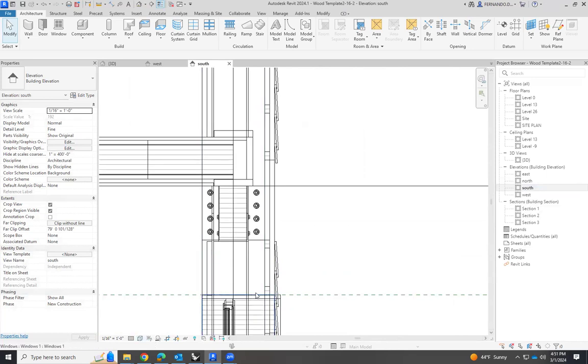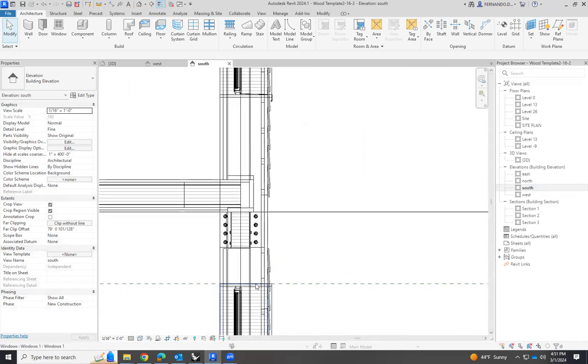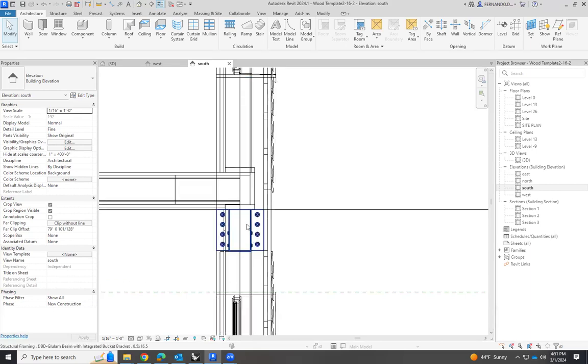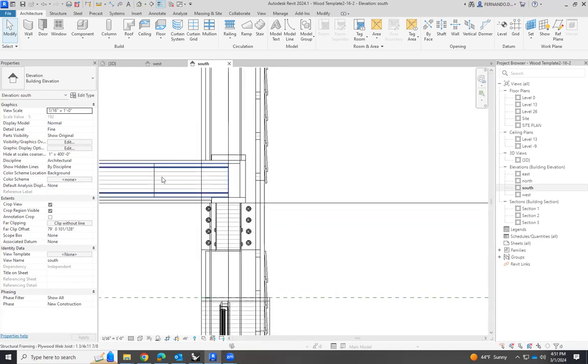So that's the window frame, that's the cavity. So I'm going to place a thermal insulation from the top of this window until the sill of this window on the second floor. So I have to fill this cavity because the beam is this one, that's the beam. And I have thermal insulation here. This is wood, okay, that's fine. So here I have to place more thermal insulation. So let's do it.